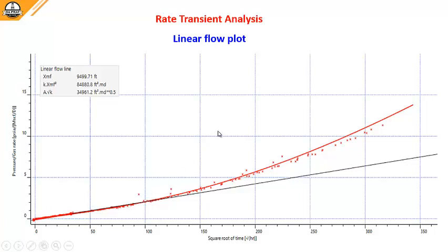And nowadays this is very popular to use to monitor if the fracture is becoming damaged with production time. As you know, in a conventional reservoir, there is a situation with the stress dependence, and therefore the fracture itself with time could be subject to a big stress and therefore lose its conductivity properties. So this is quite used for monitoring.